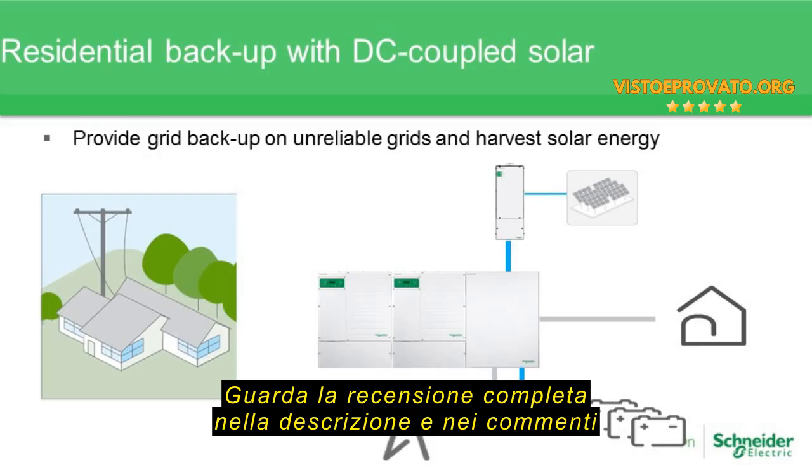And so that's why you'd have a pair of inverters in this example to cover all the loads inside the home. But then think about, not that we always have 50 amp loads, but let's say we had half of that, 25 amp loads at 230 volts. Suddenly that's a very large amount of power being consumed off of that system. So the question is, is the customer really interested in investing in that large of a battery bank to cover those loads for whatever their expectation is?